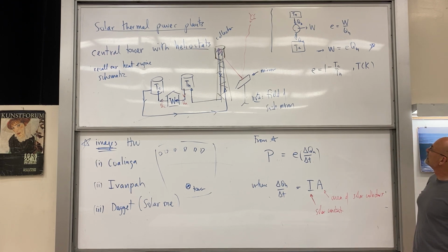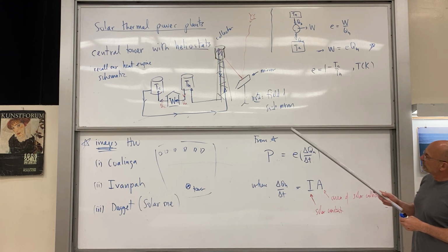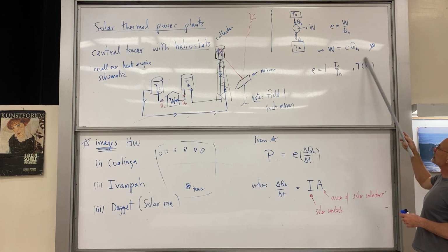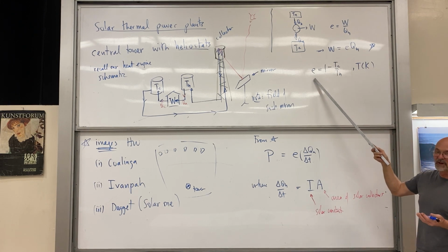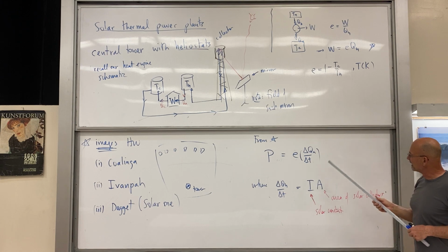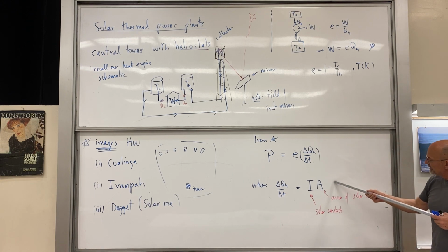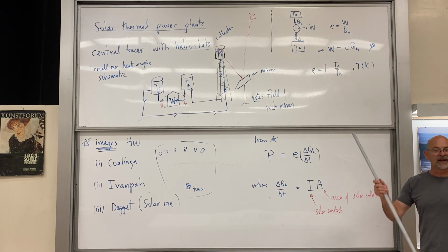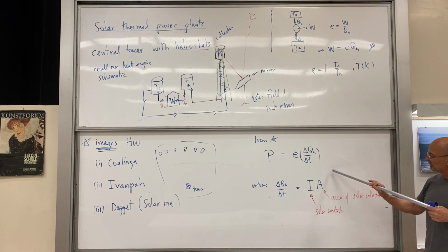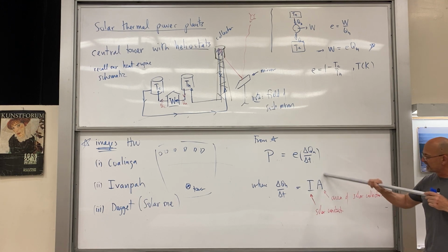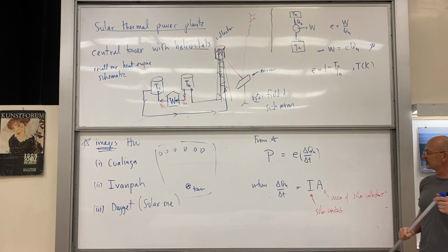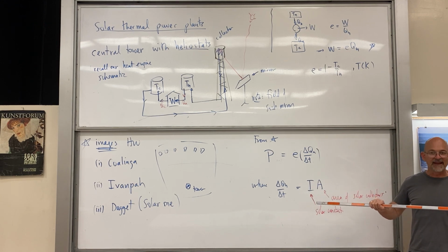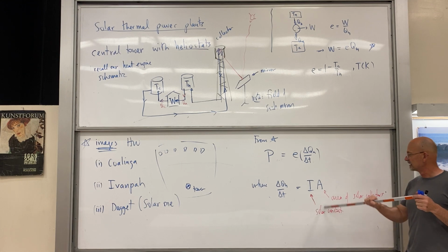So that's how it would actually be done. If we knew these temperatures, we'd get this maximum possible efficiency, so that would be a number less than 1. And then if we knew the area, we'd multiply it by the solar constant. Now that's a theoretical maximum. In reality, you're going to be striving for that and getting some amount that's less. For example, you may have to average all this over the course of a day. You don't have full sunlight each day. That type of thing.